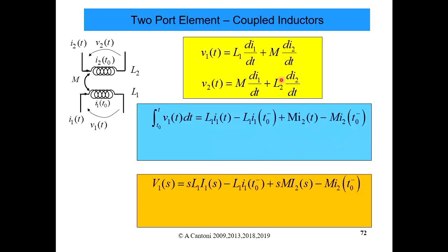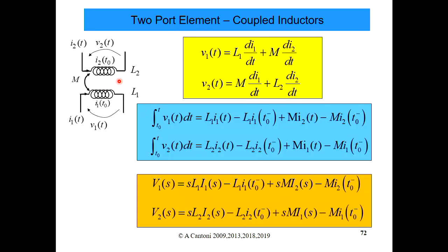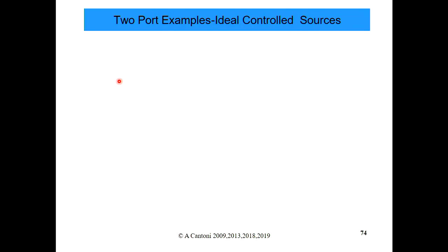A couple of inductors we'll actually go through in the second part of the course, actually deriving all these constants from electromagnetic theory. So this is a description of a transformer, how the voltages at one particular port and currents are related to the mutual inductance, which is just L, the inductance of this particular coil, the self-inductance, and the mutual inductance M, which is the inductance between the two coils. And you end up with these relationships.